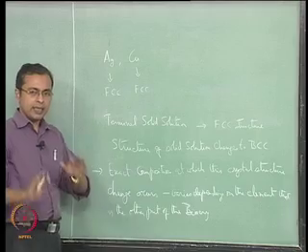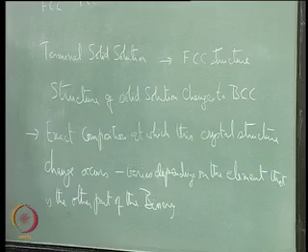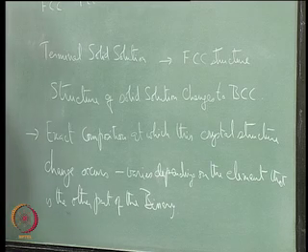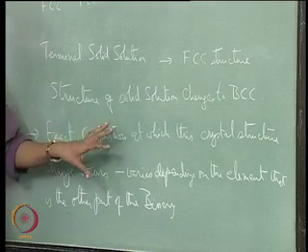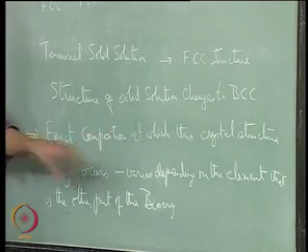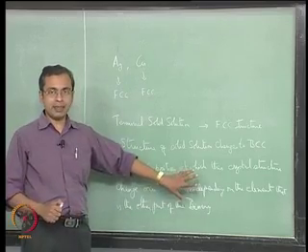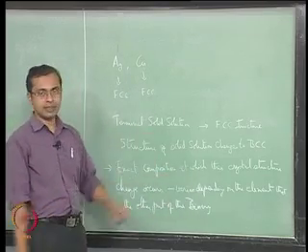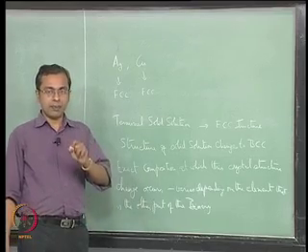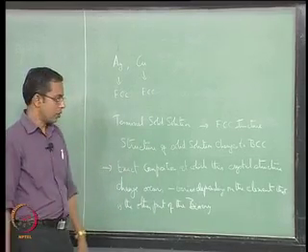So in that sense there is no great mystery there. You look at various systems, you add elements, and changes occur at various compositions. Up until this point I do not think there is anything immediately standing out. There is no immediate pattern showing up here, except for a change in structure from FCC to BCC as you add an alloying element.